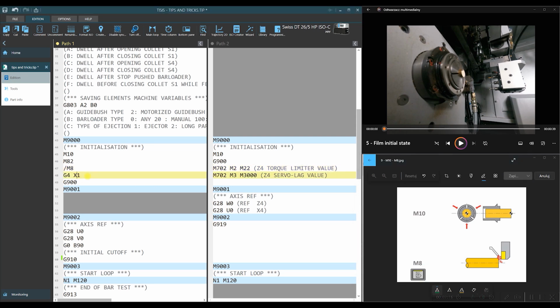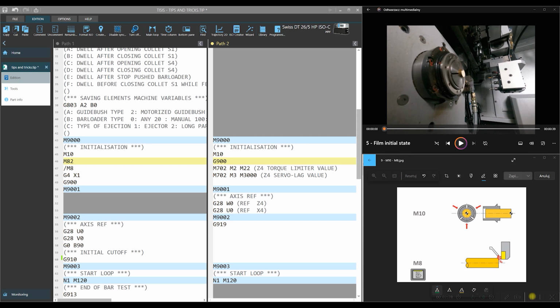Below there is a 1 second dwell, and you see Tornos macro G900 in both channels. It calculates 0 offsets for work in main and back operations and stores them in G54 and G55, respectively.